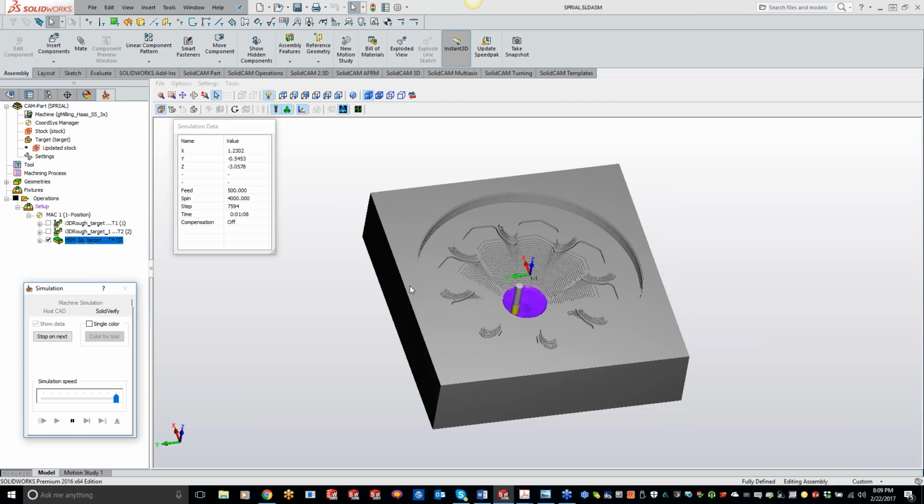So we're starting from the inside and working our way out here, doing a 10 thou step over. Now, it all depends on surface finish for you guys. If you're looking for a mirror finish, go that 5 thou, maybe even up to 8 thou, but 5 thou or smaller. It's going to give you that mirror finish. Just remember, the tighter you make that tolerance, the longer your cycle time will be.